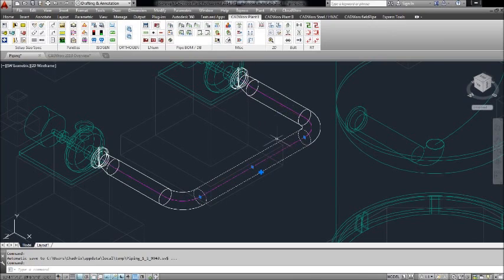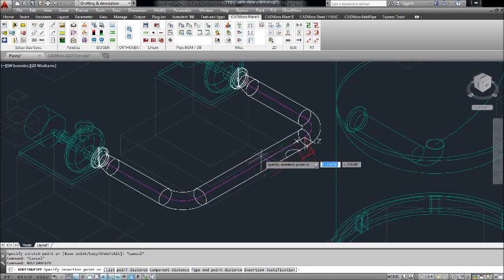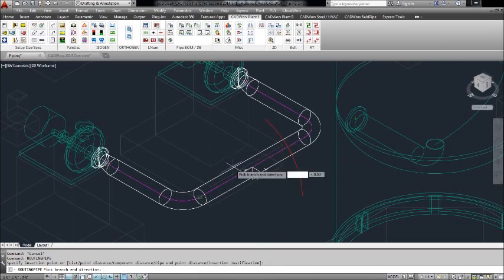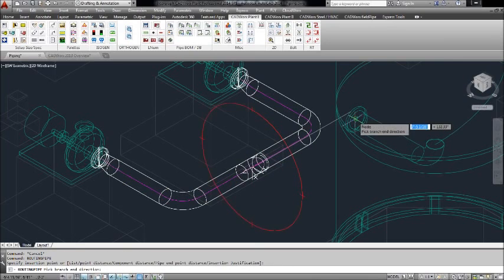So now that I've got my pump to pump done, I'm going to activate the plus grip on the middle of this pipe run right here to get a T so that I can run over to the nozzle on my vertical vessel. Now, if I knew this dimension, I could type it in, but while we're sliding the T along the pipe, we can click any point in the model to align with that given point. So if I want to come straight over and up to this nozzle without making any more turns, I can click on the node on the connection point for the nozzle, and CADWorx will align that T with that nozzle point.